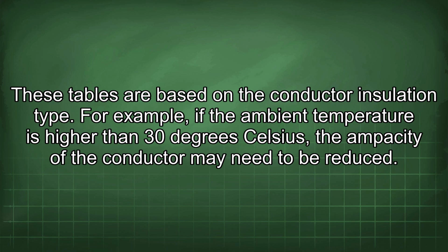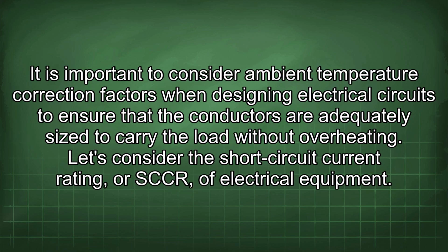For example, if the ambient temperature is higher than 30 degrees Celsius, the ampacity of the conductor may need to be reduced. It is important to consider ambient temperature correction factors when designing electrical circuits to ensure that the conductors are adequately sized to carry the load without overheating.